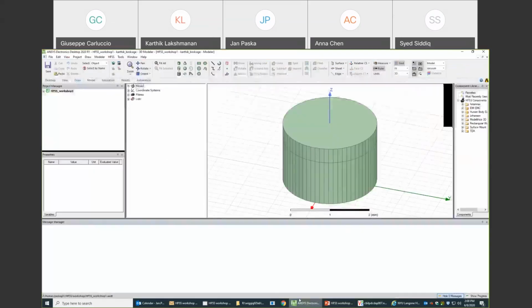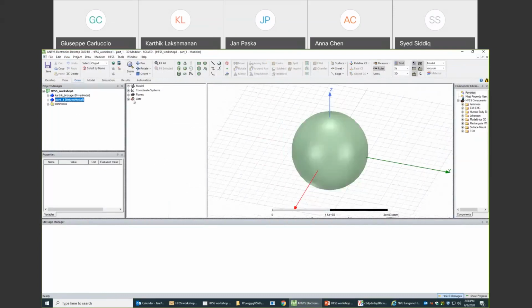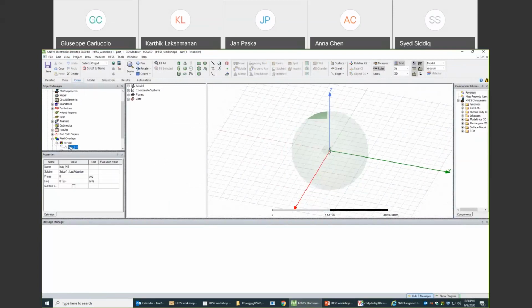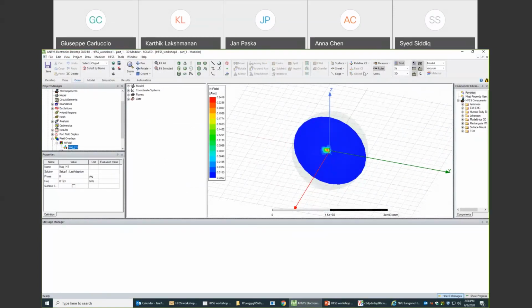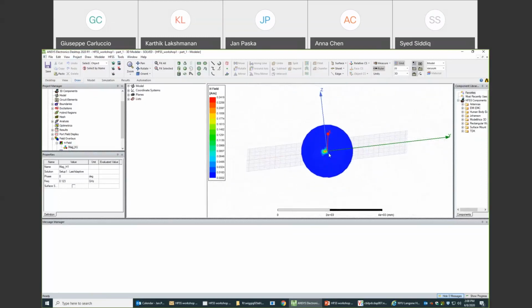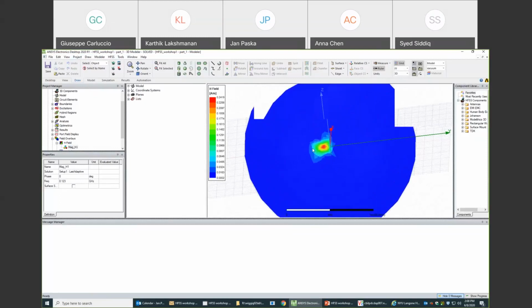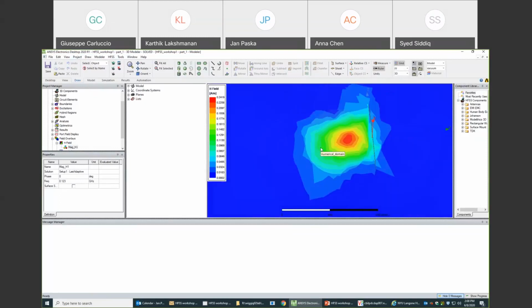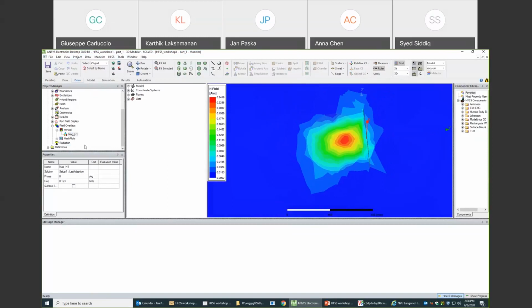Last time, if you remember, we simulated our first loop coil, and we plotted this magnetic field. We saw that with the initial mesh setup, we get kind of a messy result. The reason for that is, when we looked at the mesh, the mesh probably wasn't good enough.